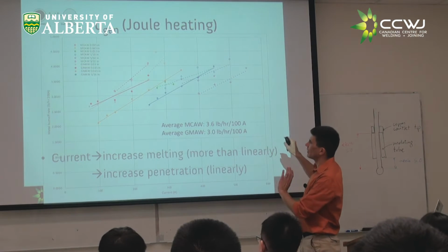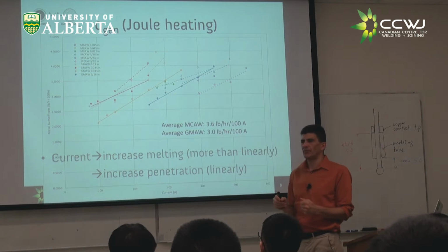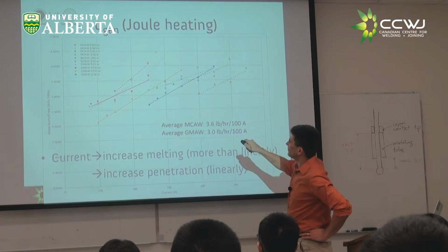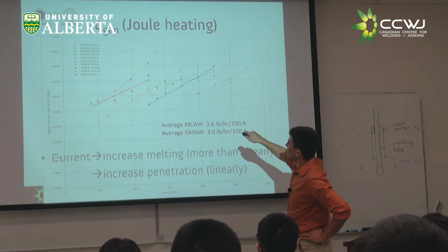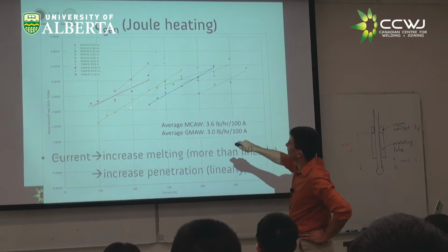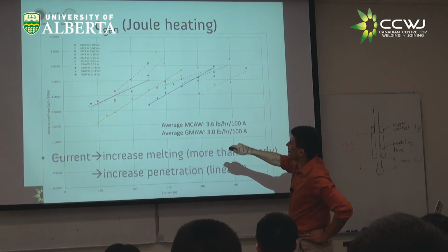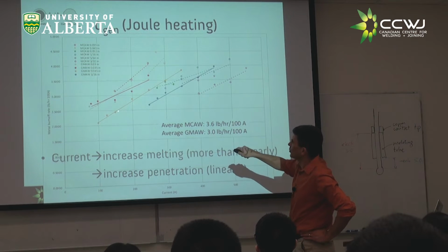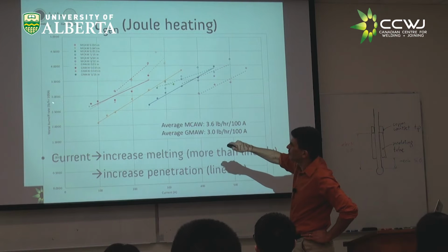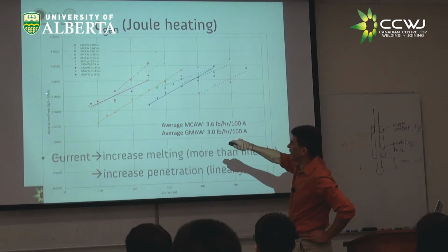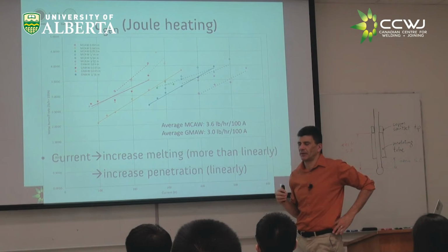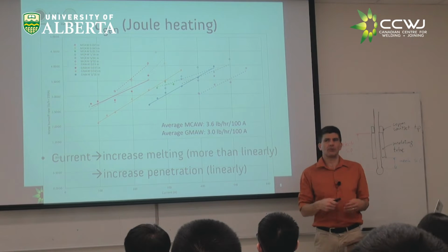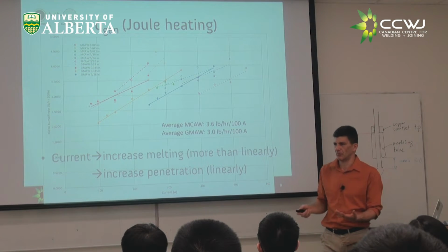So these curves that I'll explain to you in a second, they all come from experimental data from ESAB that they publish, right? And let's look at the 045 wire. Is this green one here? Okay, let's look at this yellow one. Sorry, this is the 045 wire, right? This is MIG, and it says as current in the vertical axis we have pounds per hour for 100 amps, right? And we'll see why this matters. But the pound per hour is how you measure your welder. And per 100 amps, because obviously if I put more amps, I'm going to put more pounds per hour, right?